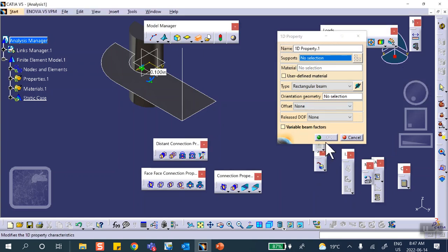And notice that I can't close it without using an orientation point. So the orientation point cannot be on the curve itself or on the continuation of it. And the reason is that you drop a perpendicular from the point to that line. If the point is on the line, perpendicular to the line doesn't make sense. So I'm going to select this one. Now, if I cannot select that corner, that's because this bugger is blocking my view, the sketch. So I'm going to hide the sketch.